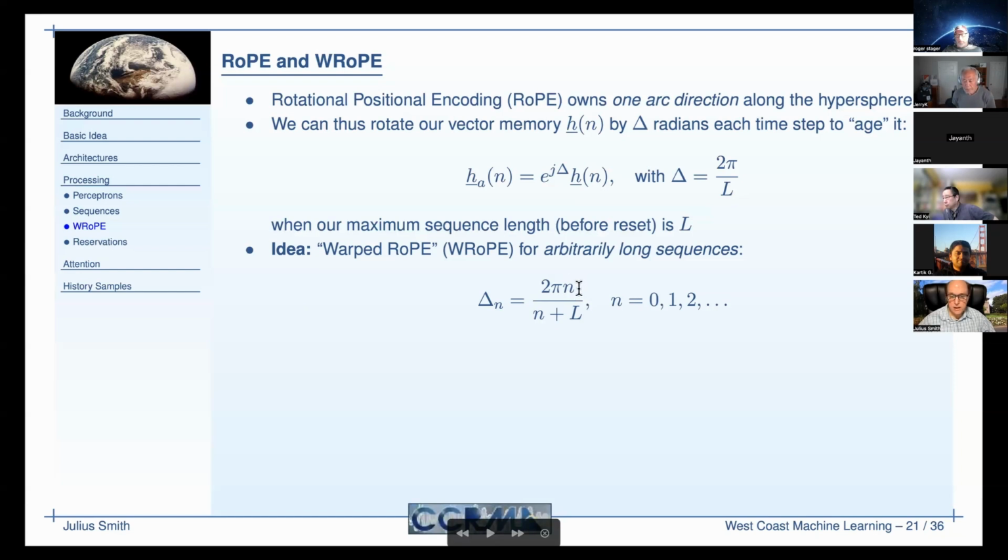In the limit, as n goes to infinity, you approach 2 pi, but you never get there. That's very much in the spirit of a bilinear transform for filter design, which takes the S-plane frequency axis, which is infinite, and maps it to the unit circle in the Z-plane, which is finite. Everything's fine at low frequencies where the map is fairly linear, but as you go up towards half the sampling rate, it gets compressive like this, and you never make it. So infinite frequencies are mapped to Z equals -1.